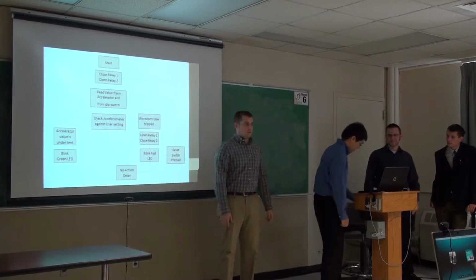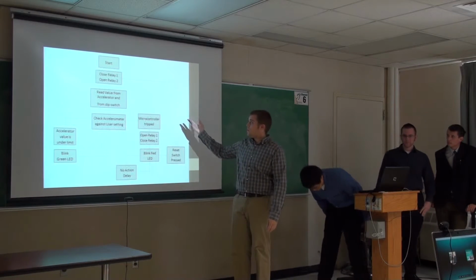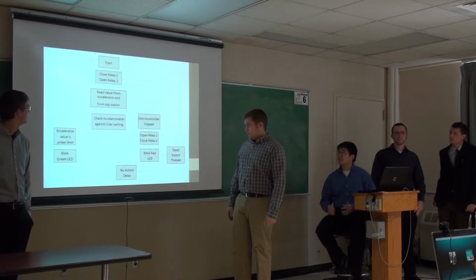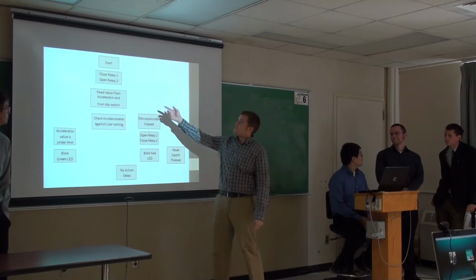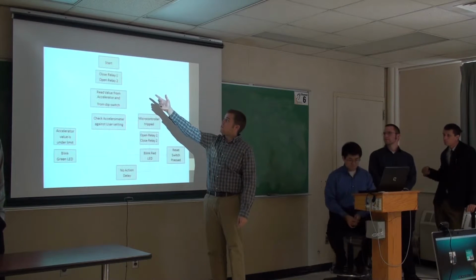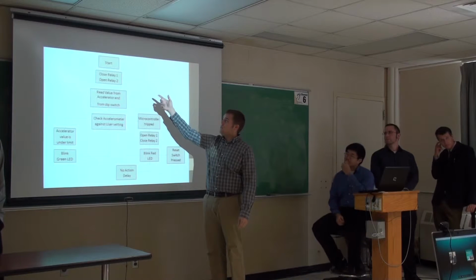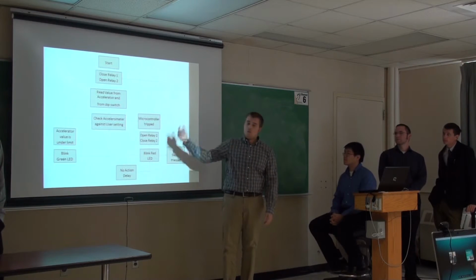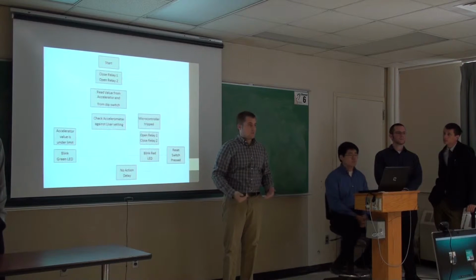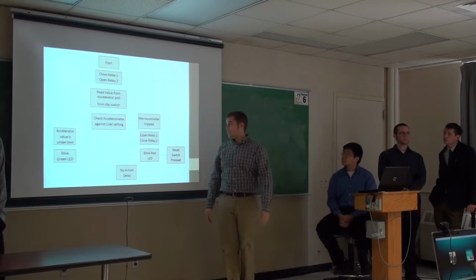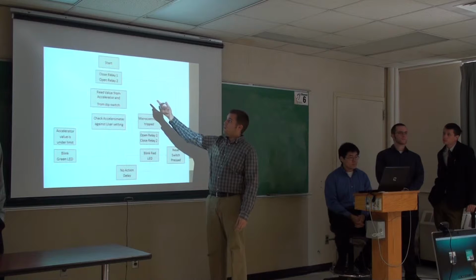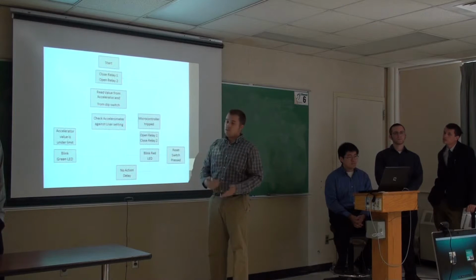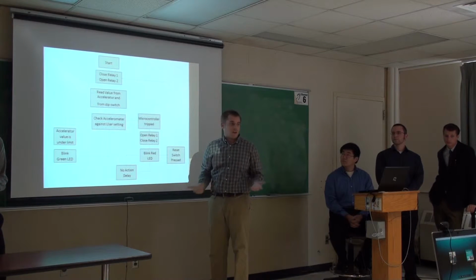Hi everybody, my name is David Eaton. I'm going to talk about the code flow. What we want to do with the C programming is first start it off by closing relay 1 and closing relay 2. Basically, that's the startup of our motor. By closing that first relay, we're going to initialize the motor, the pump, and get it to start running. And then by opening the second relay, we're acknowledging that it's starting up.